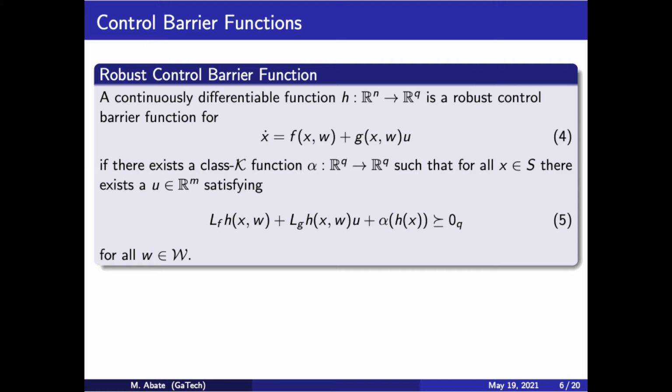So what we're going to do in this work is we're going to take some of the mixed monotone systems theory that allows you to construct a deterministic embedding system from your initial dynamics, and we're going to mix that with control barrier function theory in order to arrive at a runtime assurance mechanism that contains a finite number of linear constraints in the program. So in this way, we are able to attain a runtime assurance mechanism that is practically implementable for systems with disturbances.